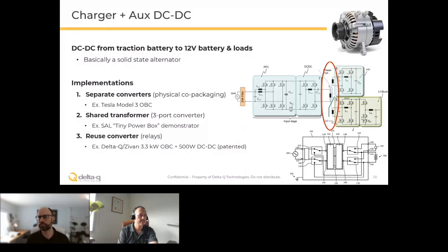Maybe I'll just quickly jump back to that slide as well. So if you look at topside cooled devices, and we've been following this closely, it can be an excellent solution, but there are a couple of gotchas. One is that it becomes difficult to second source the parts. There are only a couple of big vendors who are offering topside cooled devices right now, and it's not necessarily the same package.